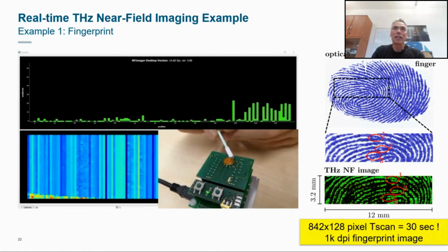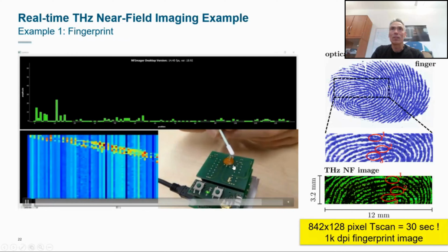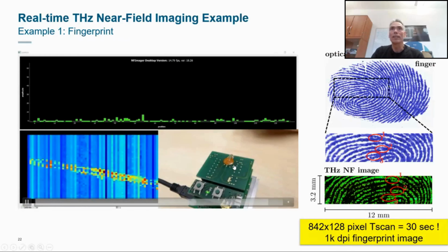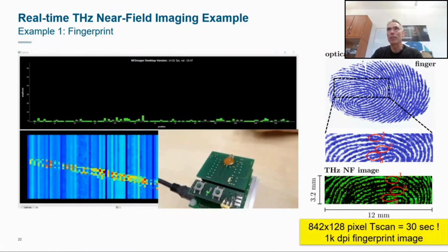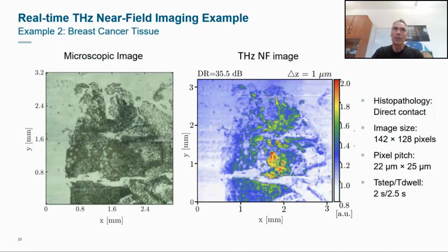You can also clean the sensor surface. You can put some isopropanol on it, and you can see the response time of that sensor for that treatment.